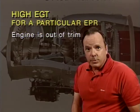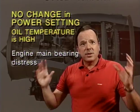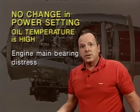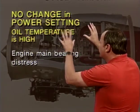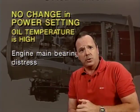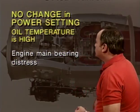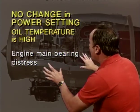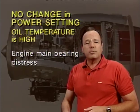Now, when a turbojet engine indicates no change in power setting parameters, everything's the same, EPR's the same, fan speed is the same, exhaust gas temperature's the same, but in spite of all of those things being okay, no change in power setting parameters, the oil temperature is high. What would be a cause of that? Well, one possible cause is what the FAA refers to as engine main bearing distress. You might have a bearing failure coming up, and you would know that by the high oil temperature with everything else being okay.